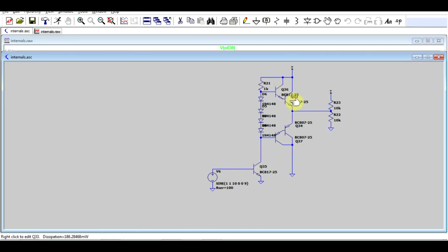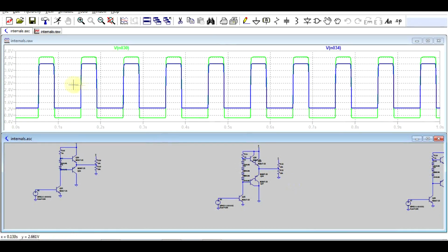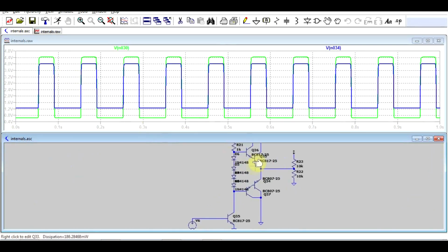we've got Darlington transistors both on the high side and on the low side, and our output limitation will be even worse. So this time we're no longer having to drive only one PN junction, but two PN junctions, both on the high side and on the low side. And with this sort of output stage, we've got a symmetrical limitation of around 1.2 volts. Again, depending on how well the circuit is designed and built.